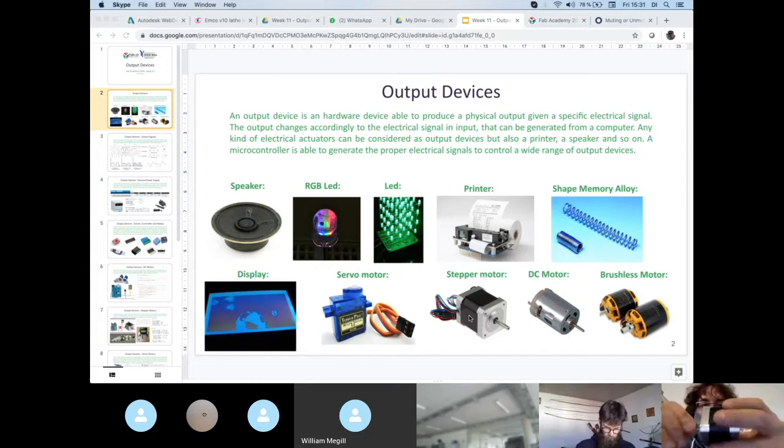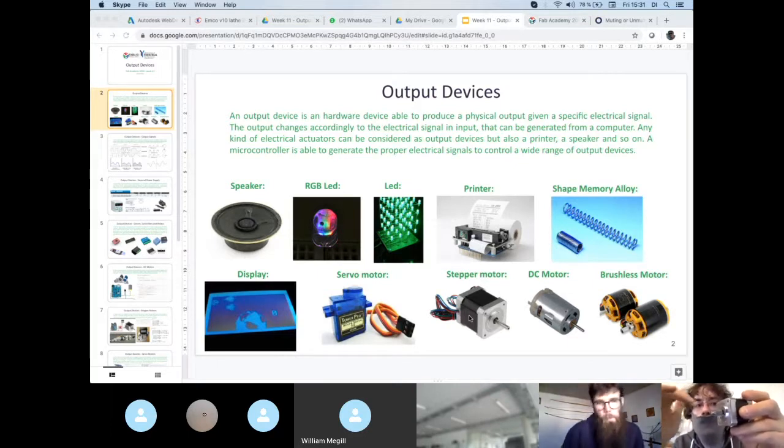One characteristic of stepper motors is that they have a lot of torque from the beginning. So from very low speed, it has a lot of torque. It can move, let's say, heavy loads from slow speed. A drawback of this motor is that the faster it rotates, the more torque it loses. So it cannot rotate very fast, first, and second, the faster you rotate, the less torque you're going to have.